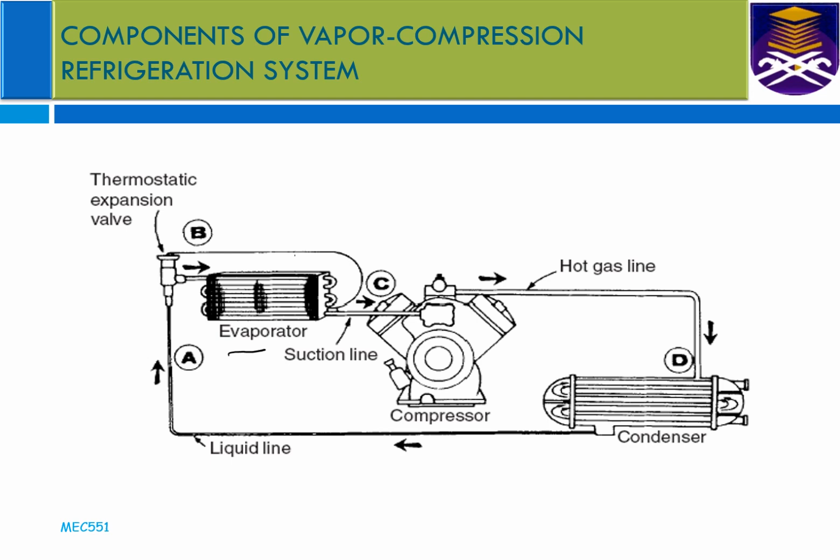The flow goes to the evaporator, which absorbs heat from the refrigerated space, and then is compressed in the compressor, giving the hot gas line, which supplies the refrigerant, let's say R134a, into the condenser, where heat is rejected to the surroundings.